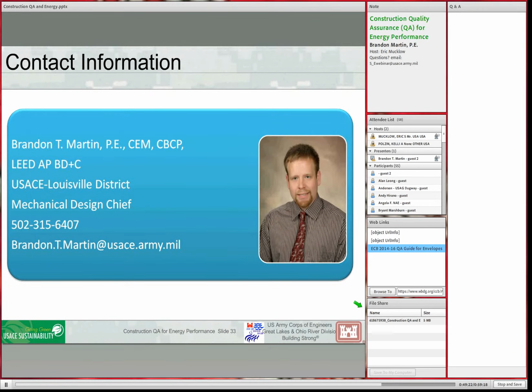Next one says, who provides the funding of the HVAC commissioning? Okay, so for Army projects, typical commissioning is funded by the construction funds. So the funds identified in the 1391 for construction of the facility, commissioning costs for the contractor side come out of there. If the elements that the Corps is involved with are partially S&A funded, anything that's pretty clearly quality assurance related would be S&A funded. Anything involved in design elements would be DDC funded.